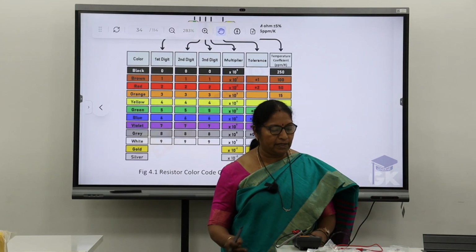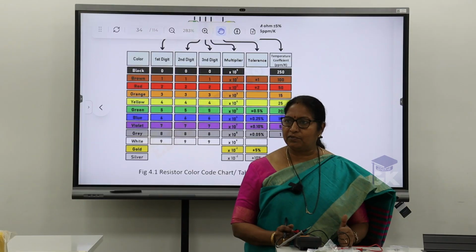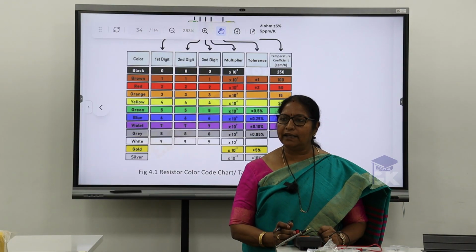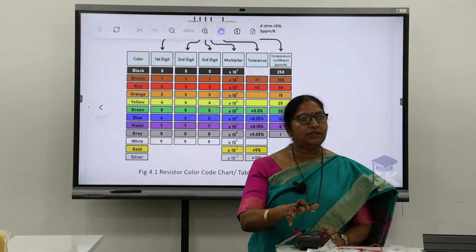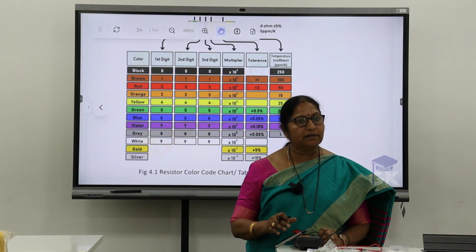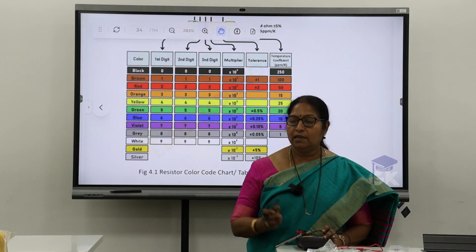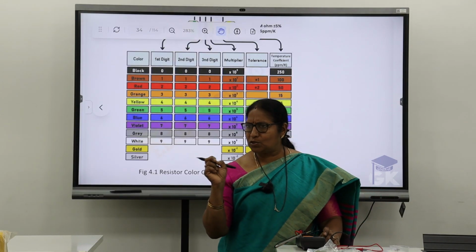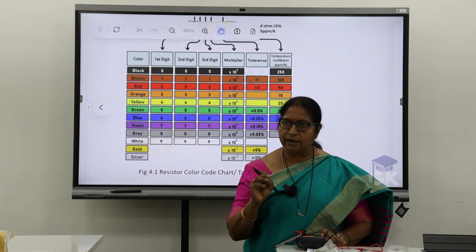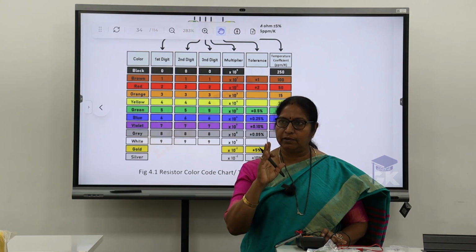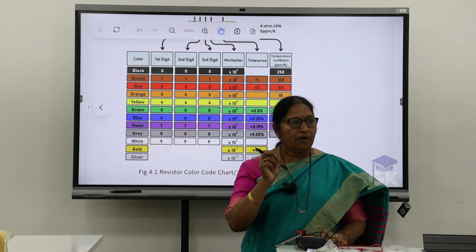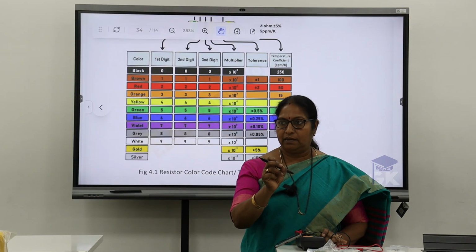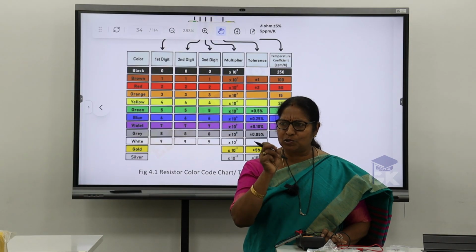You may be thinking, why do you get these different values of resistors from the same manufacturer? Even if you take the same batch, this tolerance is applied. Just look at the resistors. The resistor size is so small, whatever material they use, metal film or carbon film, the amount of material composition used for the resistor cannot be controlled so much.